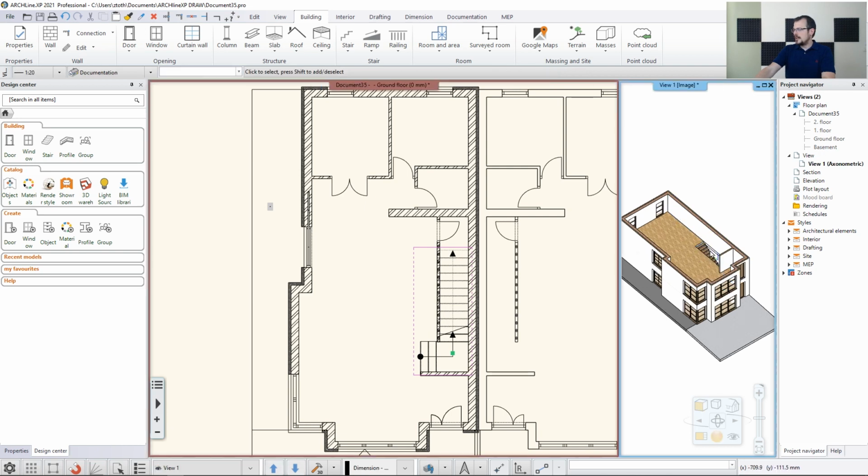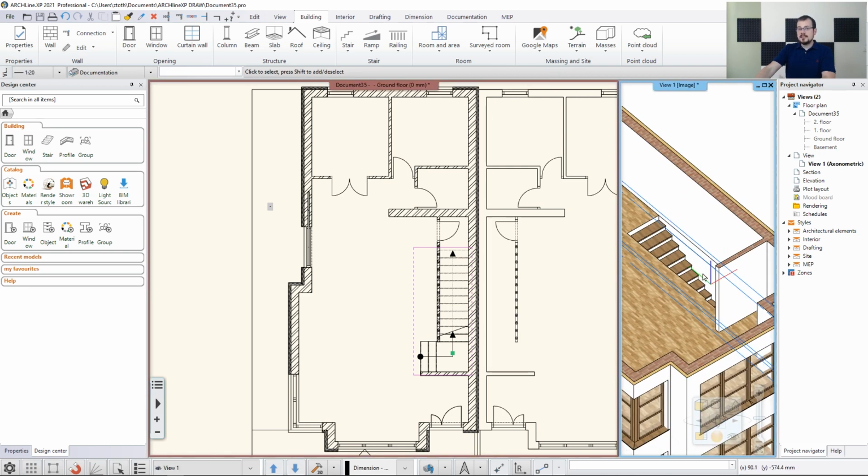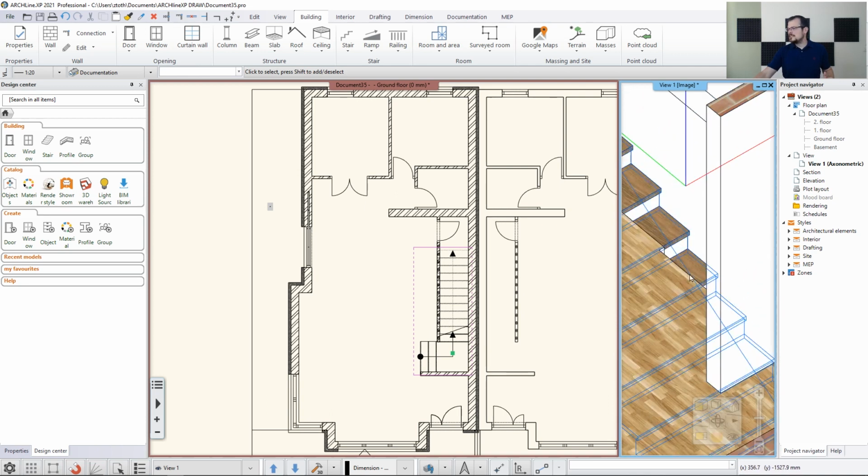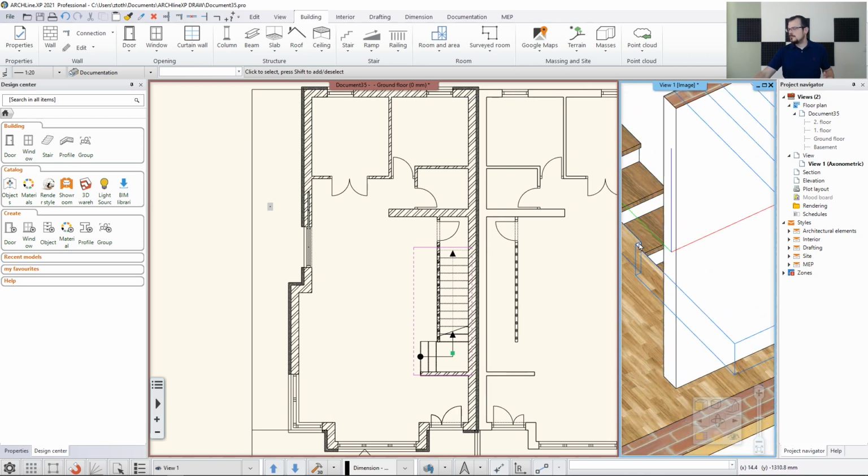Let's select the 3D and zoom in to see it a bit more. Now this is an automatic cut. How does it happen? The software actually investigates which are the steps of the staircase when a predefined value of 2100 millimeter is not met. And whenever it bumps into that kind of constraint, it's going to just cut the slab this way. But if I zoom in a bit further, I see that there's one thing in this cut which I don't really like. I need to adjust it.